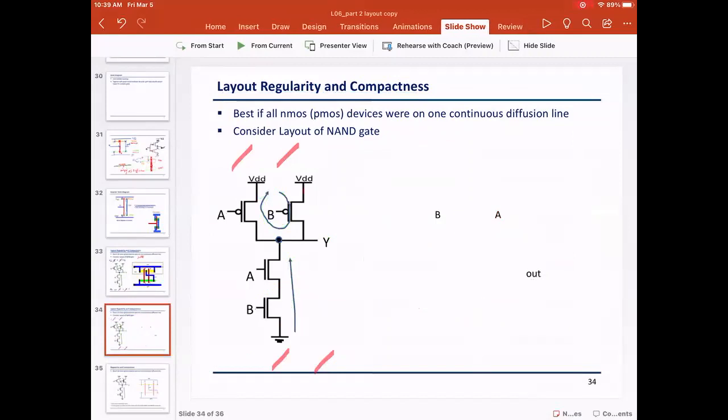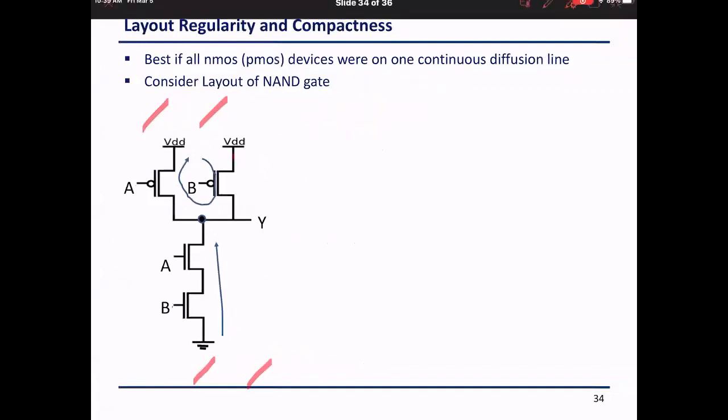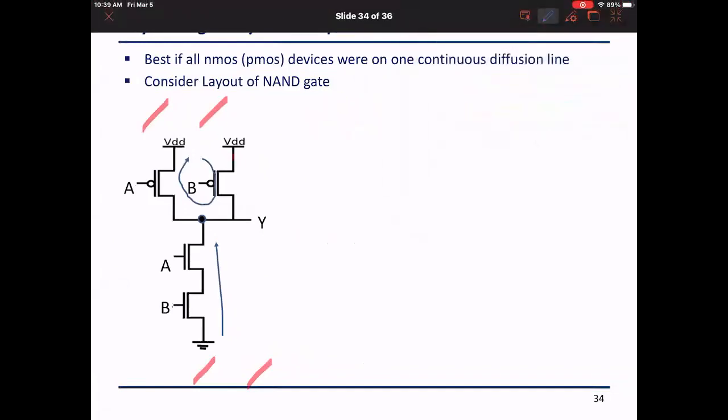Sorry, one second, so that it is clear for you how we draw the stick diagram now. Since I have one path, I'm going to write them again, it's okay. Here we said VDD, B, Y, we visited transistor A, then we came back to VDD. And here we had the ground, then we went to B, then we went to node 1, and then we visited transistor A, and then we visited node 1.